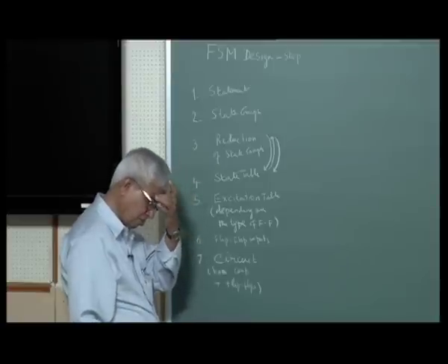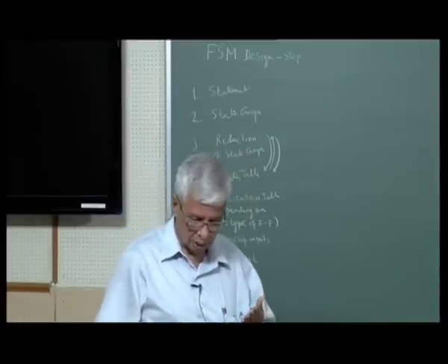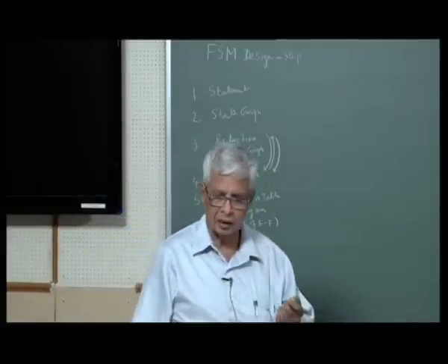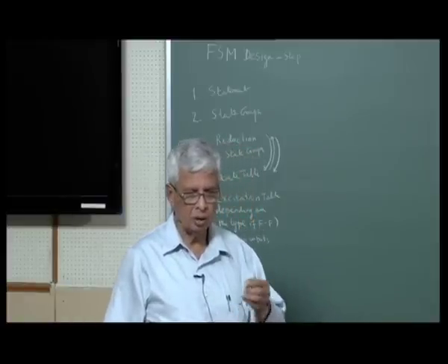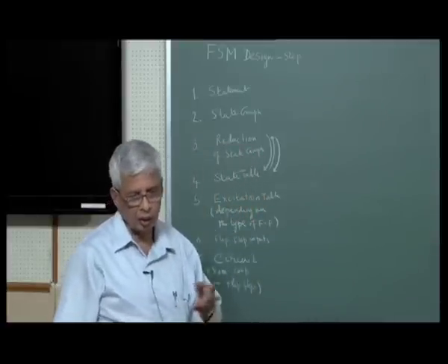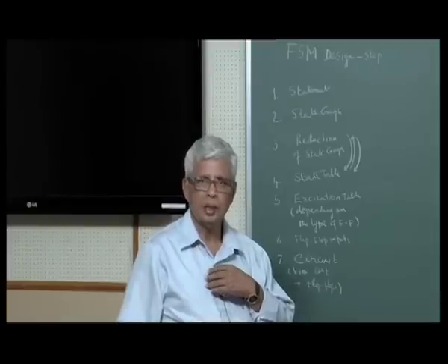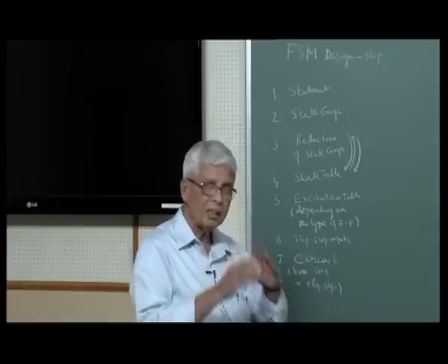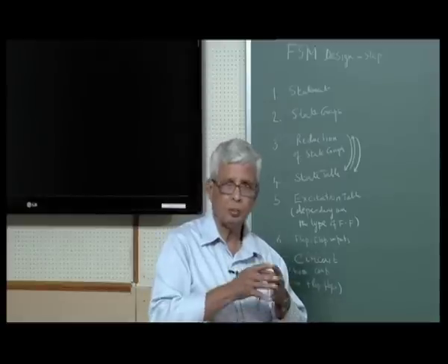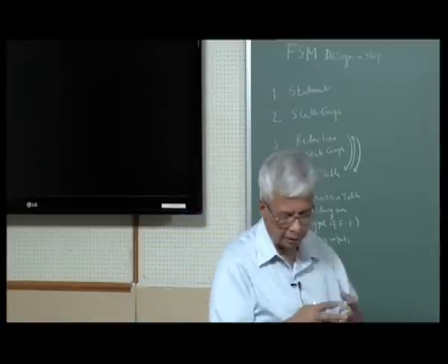We started with the state graph which is regular, like a counter. From there we were able to design the machine using state table and flip-flops. Then last class we saw the counter which is non-sequential. That also we saw how to do that. Then we saw last lecture, given a state graph with input output and the number of states defined, you know how to do it because you know how to write the state table, and from there how to get the excitation table and so forth.